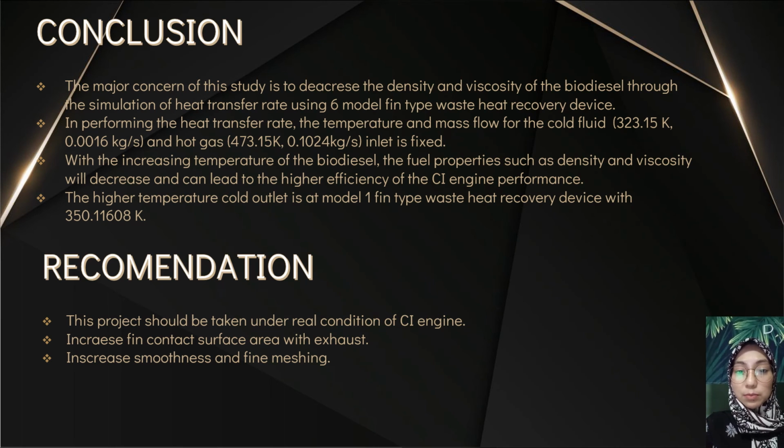For a better and more accurate result, this study is recommended to be done under real conditions of the CI engine, or to increase the fin contact surface area with the exhaust, and or change the exhaust material type from steel to copper for a higher heat transfer rate efficiency, and increase the smoothness and fineness of meshing.